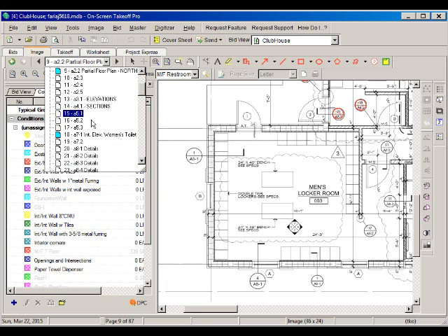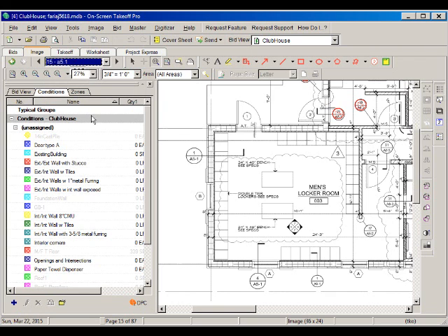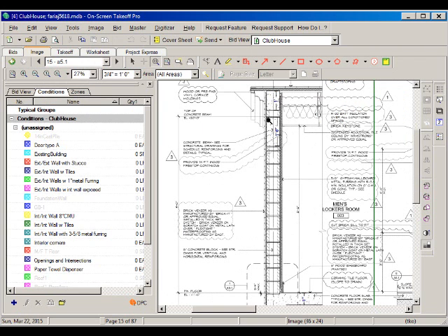So let's go again to A51 and say if we have a 9 feet elevation up here, right? It's going to be 9 feet elevation for the top of the beam, and then we have 8 feet 6 inches inside for the suspended ceiling.